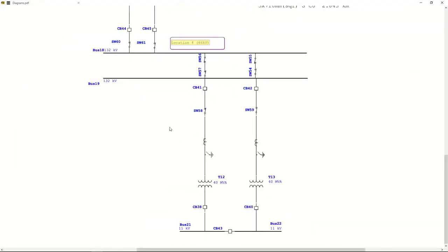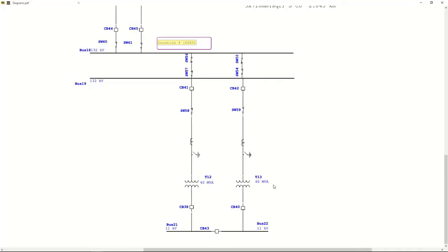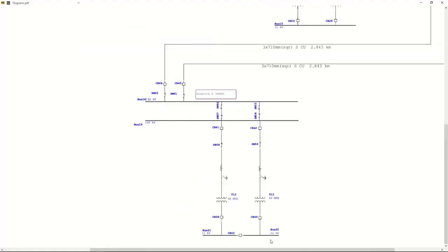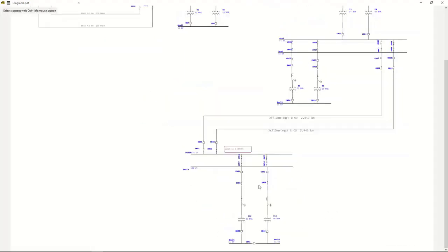You have your circuit breaker, you will have your relays, you will have everything set up there. You can see these are your current transformers that are monitoring the amount of current going in through here. So if the current exceeds, it's going to trip the circuit, send a signal to the circuit breaker. That is an entire lecture tutorial we're going to make to explain how this system works. So basically that is it. You have now these transformers here rated at 40 MVA supplying into this location. And from there you have an entire system.